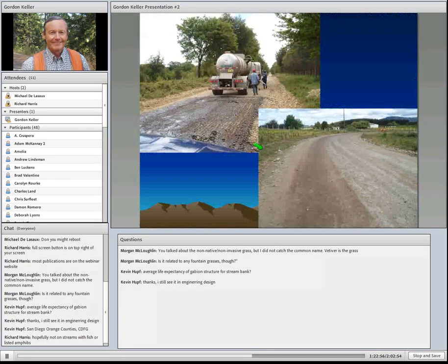More commonly, for a lot of your dust palliatives, it's just a sprayer application. You can put it down as a powder, but most of them are liquids. Spray it on the road. This is some calcium or mag chloride that's been on the road for a while that tends to get kind of white, and I've seen very good performance with that, particularly for main haul roads or collector roads getting a fair amount of use all season. And then you may have to reapply it, or apply a light treatment again in subsequent years.